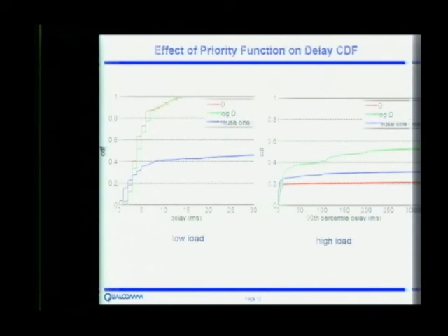So just again a simple example: 9 femtocells, and we look at the delay CDFs. We're using a couple of different functions there. This is a low loading scenario where, if you use the max iteration, you get delay CDFs which are red and green. Red is for P, green is for log P. They're essentially similar in low load. And reuse one just collapses, even though they're not full buffer, it just collapses. So you do need to partition this.